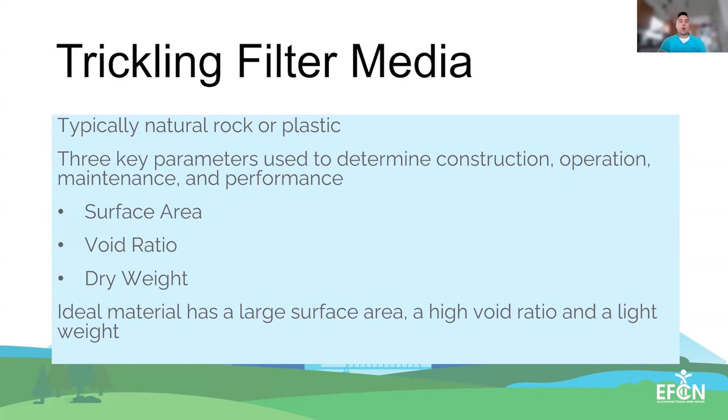Our plastic media is typically an order of magnitude lighter than our rock media. What you're ideally looking for is a high surface area, a high void ratio, and lightweight for all of our filter media. And then, of course, affordability and durability.